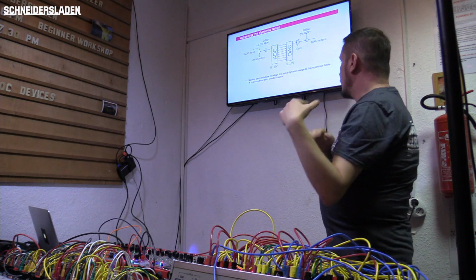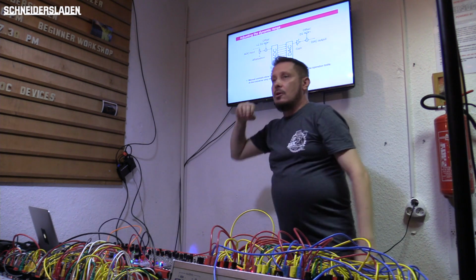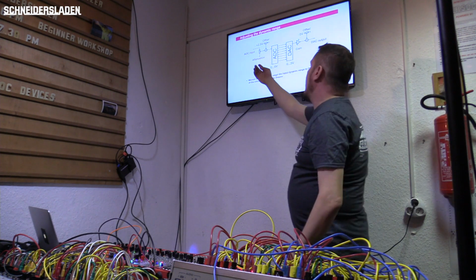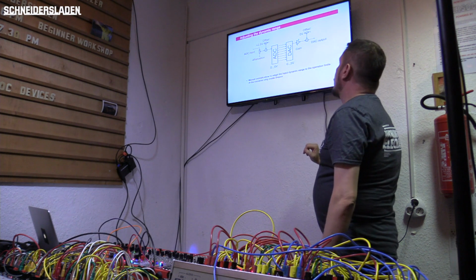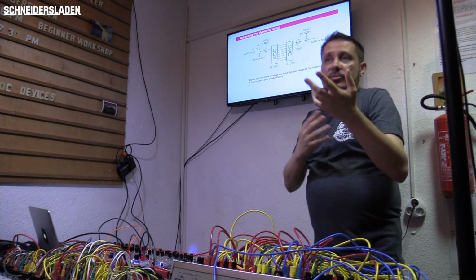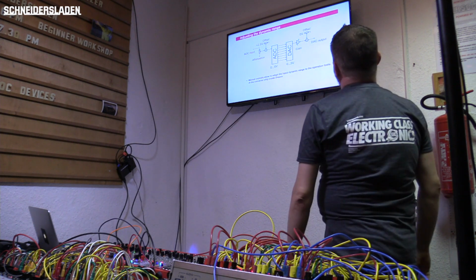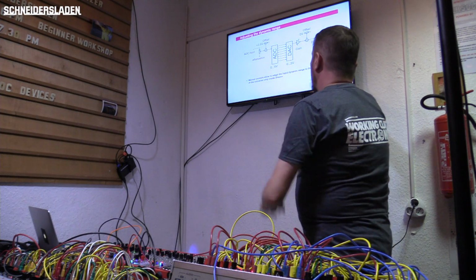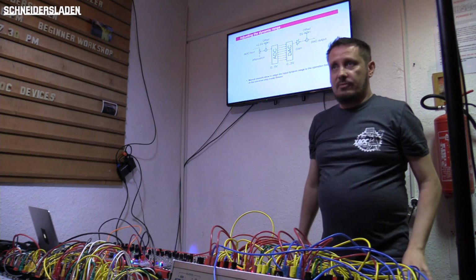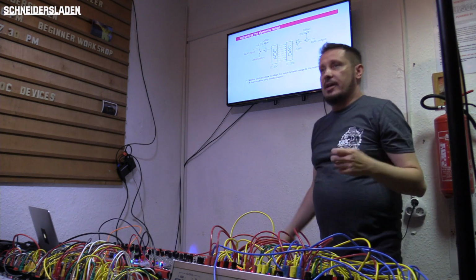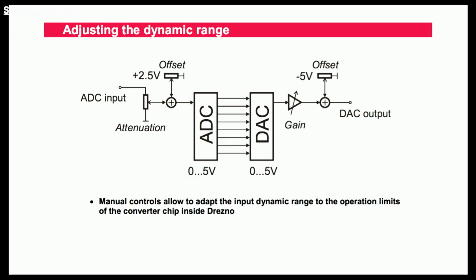So we can attenuate and offset your waveform so that it will not be clipped or distorted at the ADC, and also it allows you to bring it back to the original dynamic range or polarity or whatever you want. Of course, you can set them however you want, but in order to get exactly the same looking waveform, you need to set these very carefully.